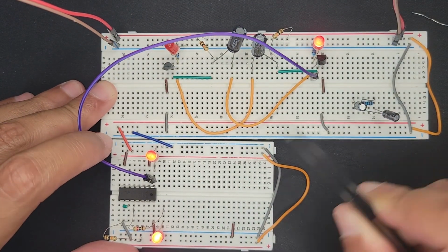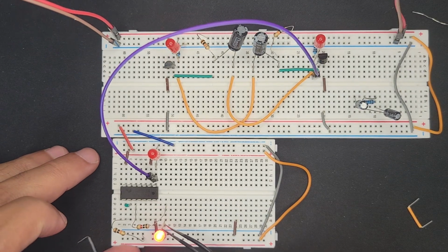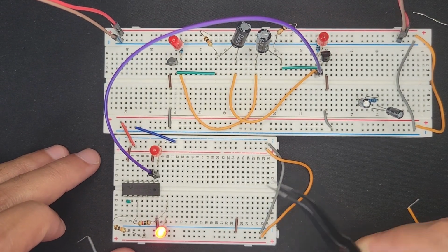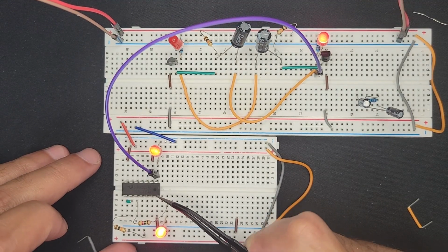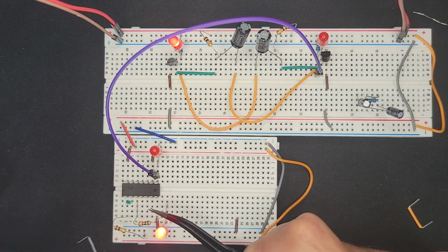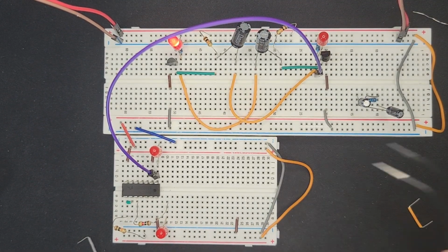We see it's in sync right now with the clock. But again, if we plug this out, then it doesn't refresh this. Right now there's a 0 coming here, and it's pulled down. So there's a hard 0 here. But the clock does not cause the shift register to bring in the new value into this first A output, the first bit. But if I tap it, then it refreshes. So there's something wrong with the signal for sure.